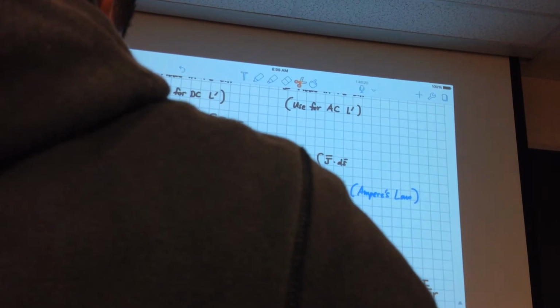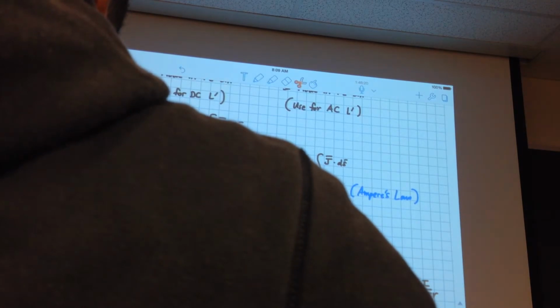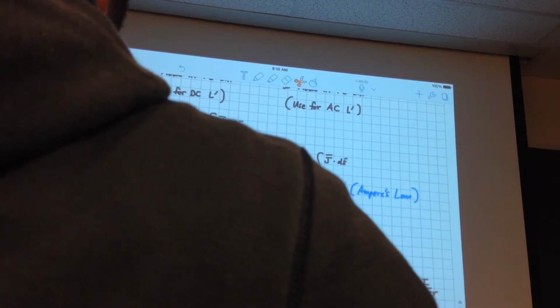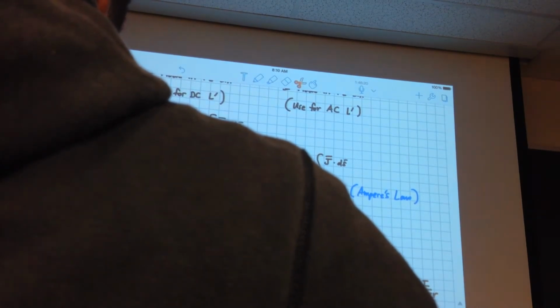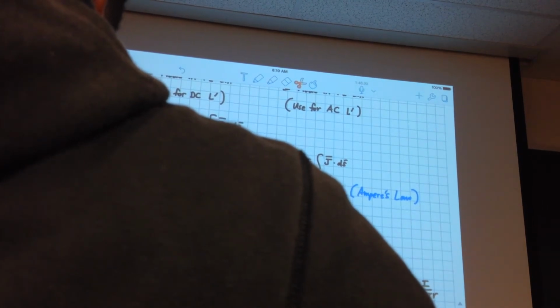So phi dotted with phi is 1. H_φ comes out of the integral, and you're just left with dφ in the integral, because for any contour, that radius is going to be constant about that contour. You have H_φ times r times the integral from 0 to 2π of dφ is equal to I, and that lets you solve for the magnetic field.